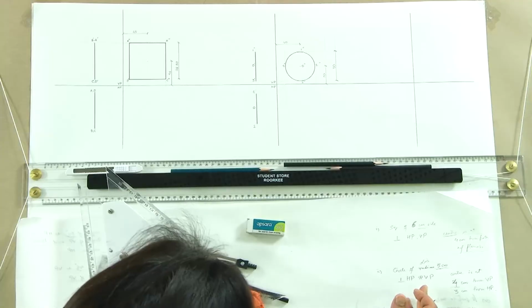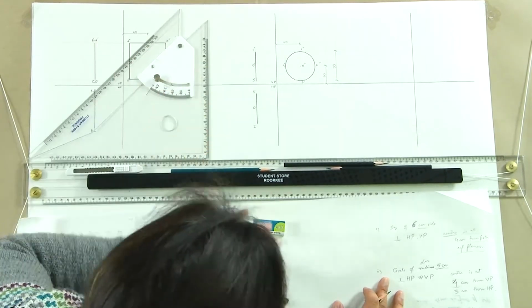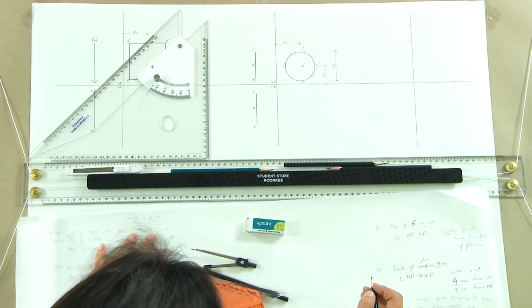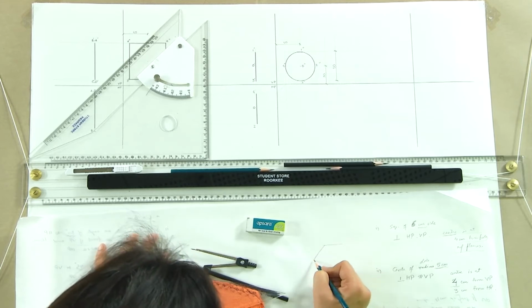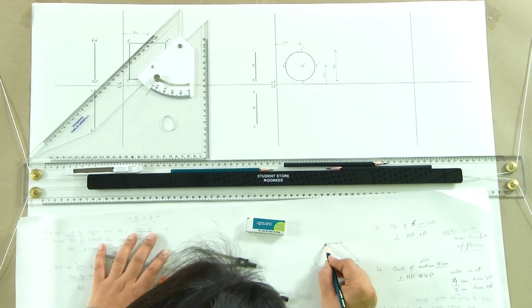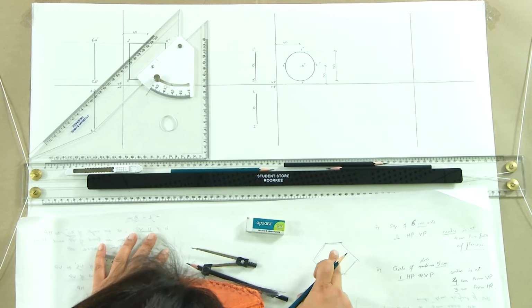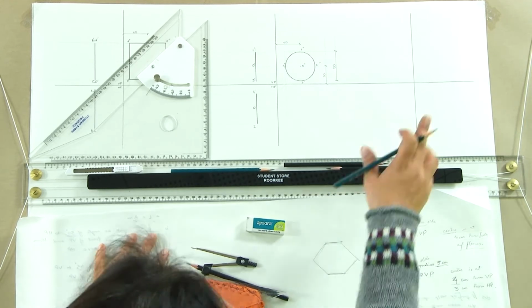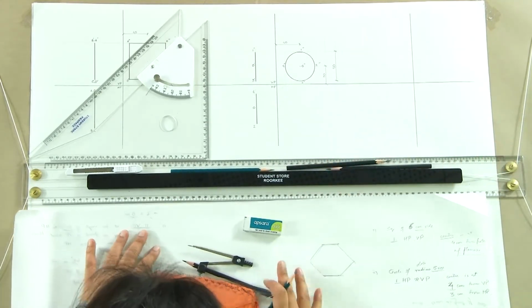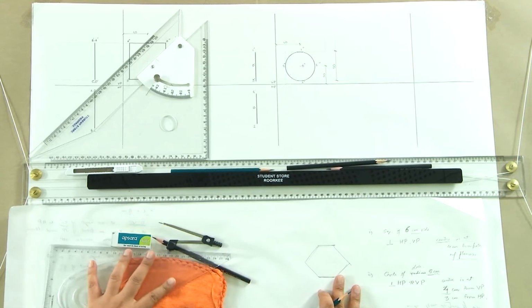Similarly, you could be drawing anything. Try drawing a hexagon which is perpendicular to both the reference planes and its 2 sides. So, when we are drawing a hexagon, 2 of its sides are parallel to HP. So, when you draw the hexagon, it will be lying like this in the side plane, because 2 of its sides are parallel to HP. So, you can start by drawing a hexagon in the side plane, and then you can have its projections drawn onto this. This is what you have to try at home.